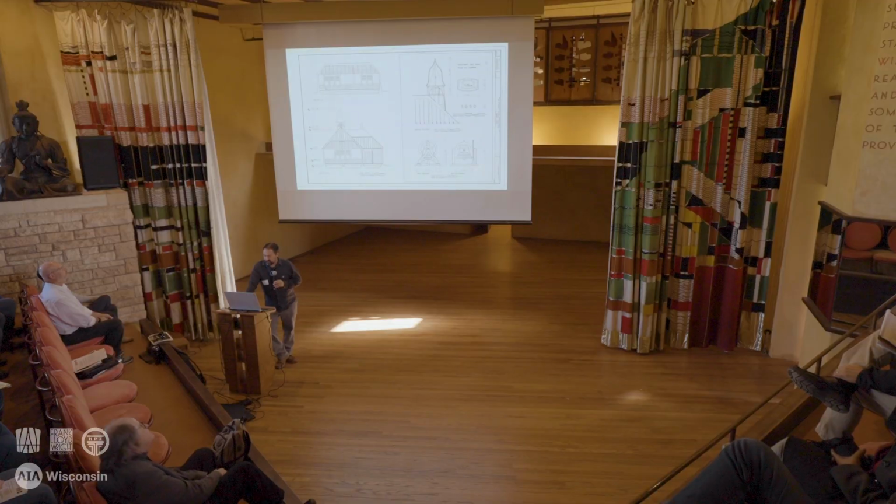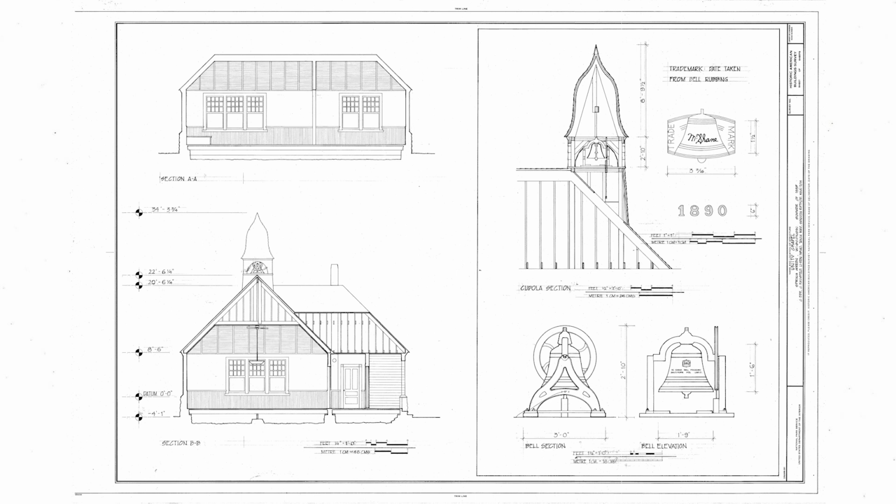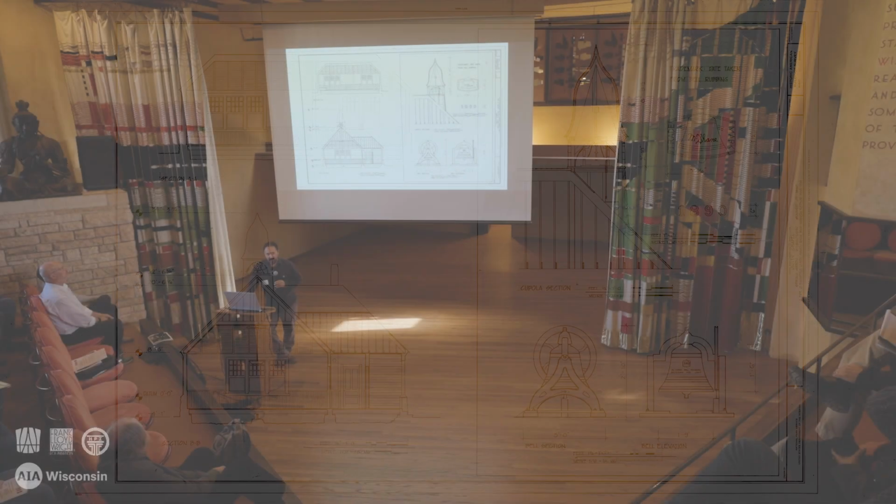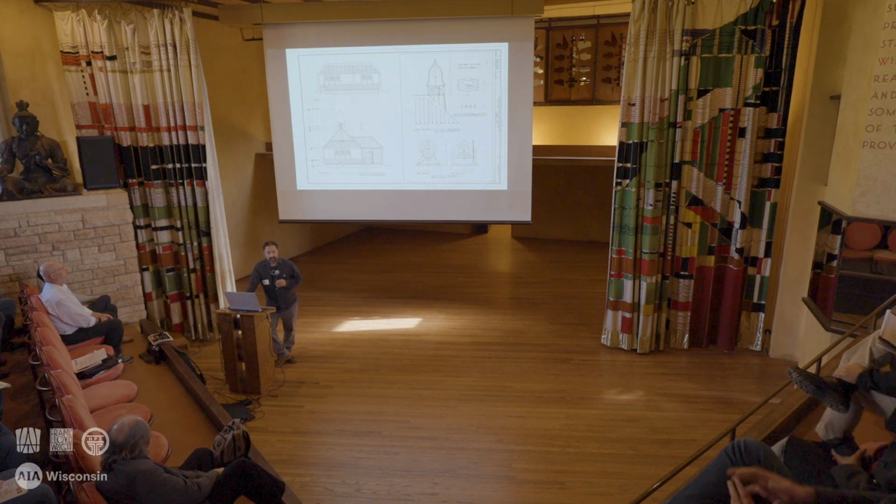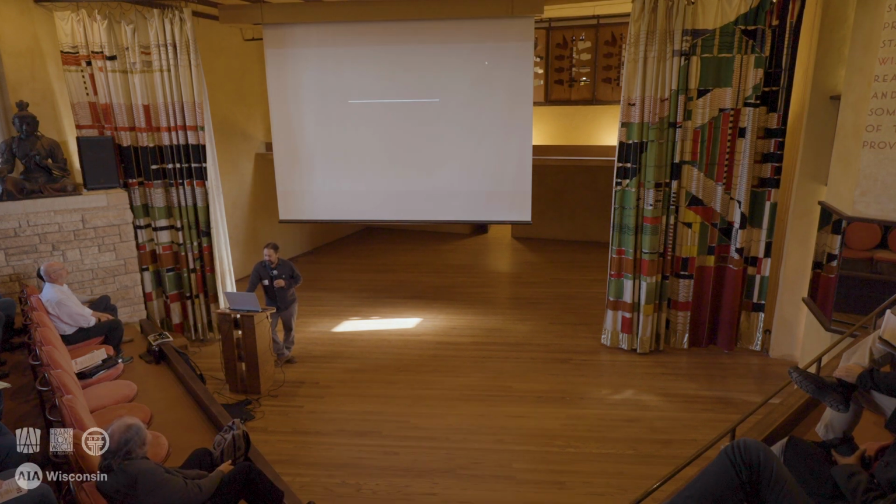And then here's just for some of the, because a lot of this it's all analysis. It's comparing data and things. Here's the HABS drawings from '95 for this building. I just want to look at a real quick overlay of what the scan data is to the HABS drawings from back in '95, where they did not utilize this sort of technology.